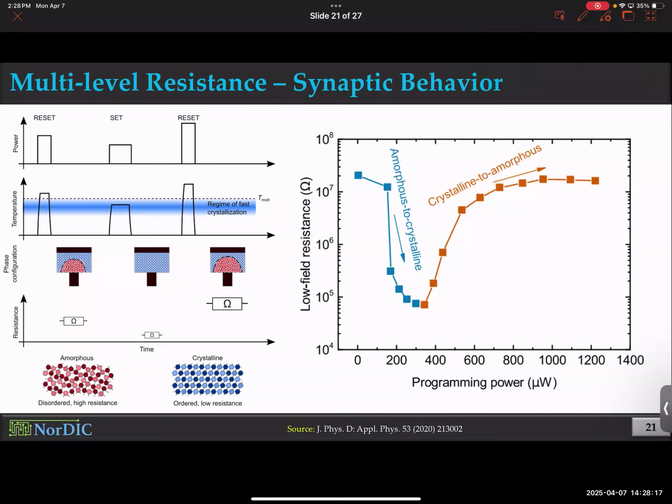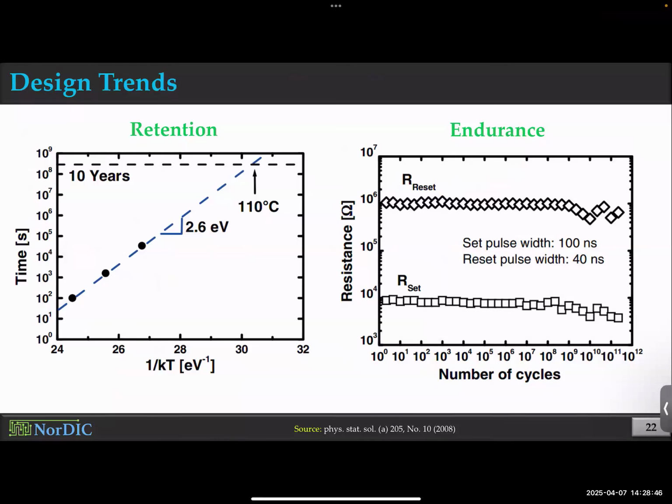See the gradual part here. If you used any other type of memory, like a DRAM, for example, you would have switched from high to low and high. So it would be like sharp, super robotic. But phase change memory, and there are some other memories out there, allows you to switch really nice and smooth. That means it's more analog because of the way things change here in phase change memory. Does that make sense to you? Okay. That's why it's a good synapse.